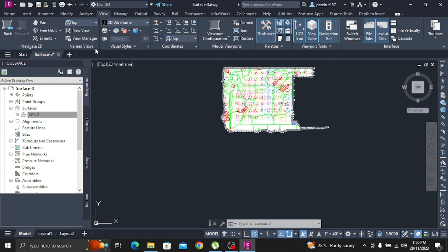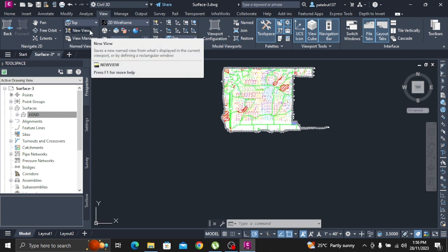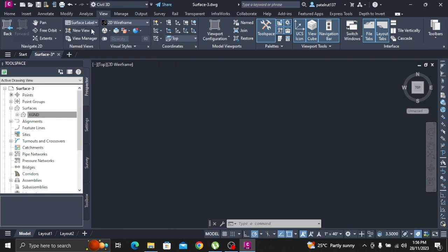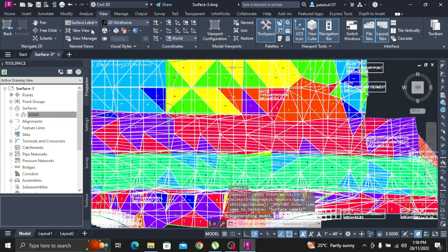Add spot elevation labels. In the Add Labels dialog box, specify the following parameters. Label type, Spot Elevation. Spot elevation label style, Standard. Click Add. When prompted, click a point along the ridge to place a label. In the Add Labels dialog box, set the spot elevation label style to Foot-Meter. Click a point along the ridge to place a label. Using the Add Labels dialog box, you can change label properties as needed while you create surface labels. Click Close.